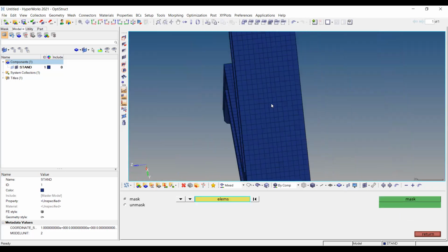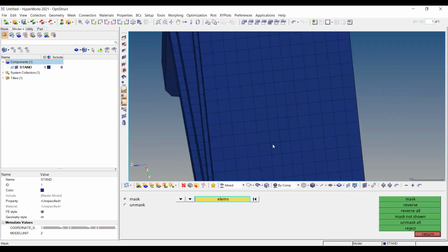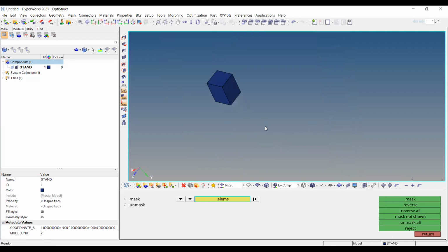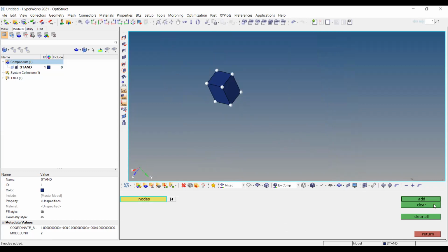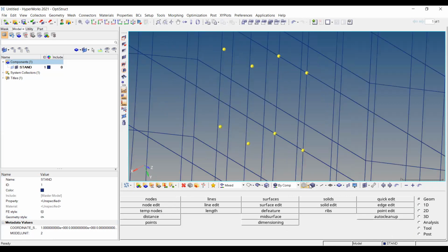There are 8 nodes required to define a hexa element or brick element. We can call it a hexa element, brick element. These are the different terminologies which we use in the industry. It requires 8 nodes. Keep it in a wireframe and observe this one, and you can count also. These four side nodes, and here also. It means for the penta element it requires 6, for the hexa element it requires 8 nodes.